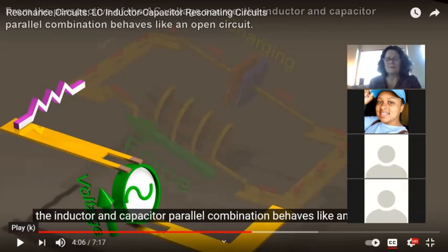So you put feedback in there, and feedback is a way of reinforcing the signal. So you put positive feedback in there, so you have some kind of amplifier with this oscillator circuit. When it gets a little bit of signal at the frequency you want, you amplify that, and you feed the amplified signal back to the input. So you can keep on getting a larger and larger signal at the input, and eventually the voltage sources and things like that will limit how far it will go. Oscillator design's kind of a black art. We'll talk about it a good bit when we get to frequency response.